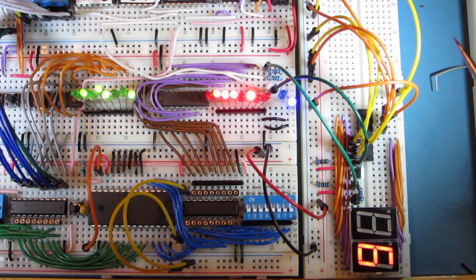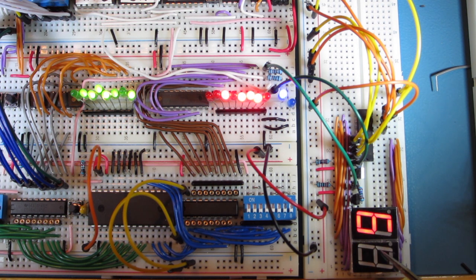And then on the input of the EEPROM, there'll be two latches. I haven't decided what latches they are going to be yet. What they're going to do is split the 8-bit data bus into two 4-bit nibbles, which then each drive the value that appears on one or other of these 7-segment displays. My only concern really at the moment is whether or not I'm going to fit all this along this bit of board, because I'd like to keep it sort of modular if I can.